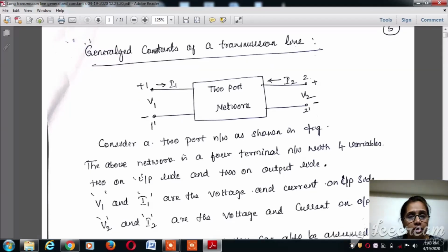So using these three methods, we understood that it is possible to consider the effect of the capacitance along the transmission lines when the transmission line length exceeds 50 kilometers and 80 kilometers precisely. So from the point of view of line capacitance, in the medium transmission line itself, we have considered that the capacitance is not lumped, but it is distributed throughout the line.